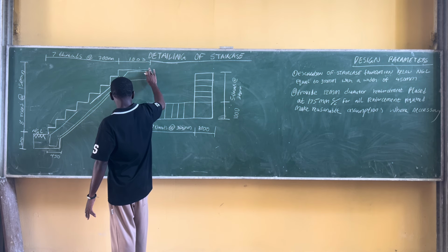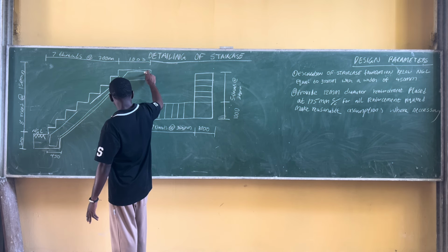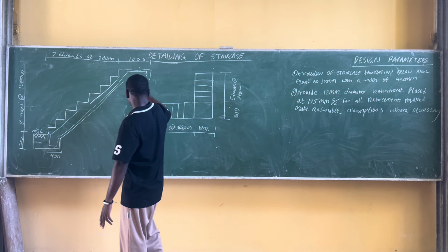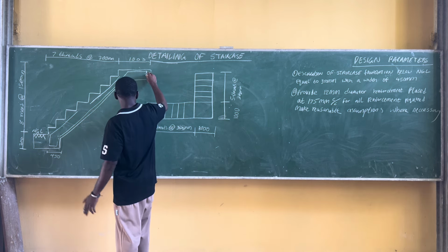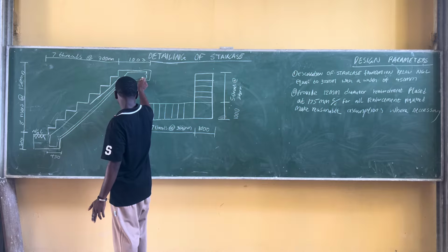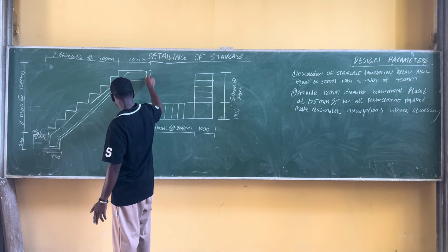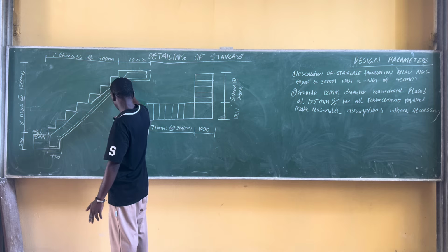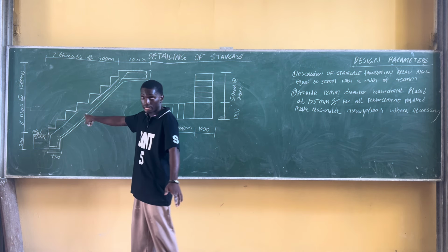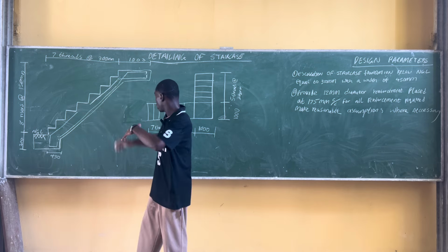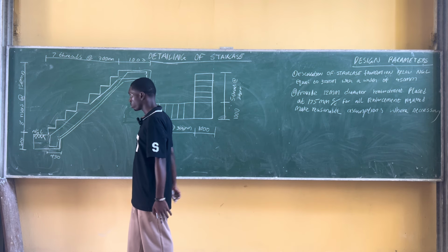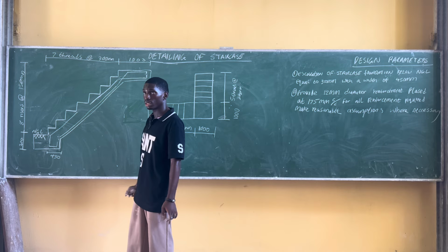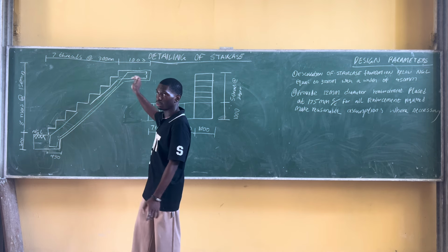Then from this slab, to cut here, there should be an opening around this middle part. Yes, the concrete cover is 30 from the slabs. Then I'll still draw another reinforcement. This is my bottom reinforcement that will turn to drop. So this is my top reinforcement, which is like this. Yes, I'm breaking because this is another different reinforcement altogether. Breaking space, no measurement.